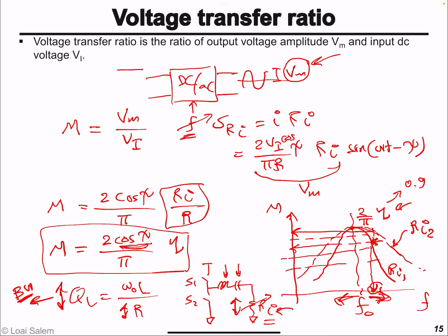So the point is, if we're going to change the frequency, it has to be via a closed control loop, so that as the load resistor changes in value, we can track that and modulate the frequency to compensate for these changes and maintain the amplitude of the output voltage at the desired value.